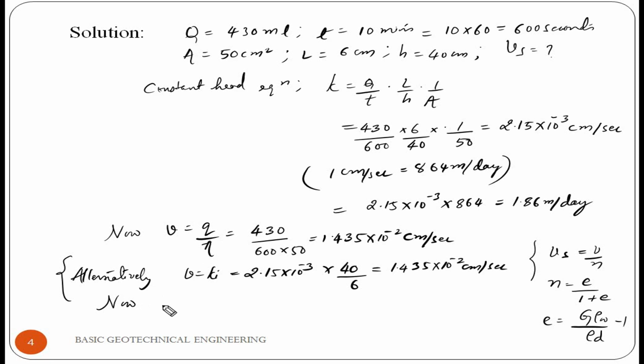So now what we can do here is rho d is equal to md divided by V, which is equal to, specimen has a mass of 498 grams, so mass of 498 grams divided by, that is volume, 50 into 6.